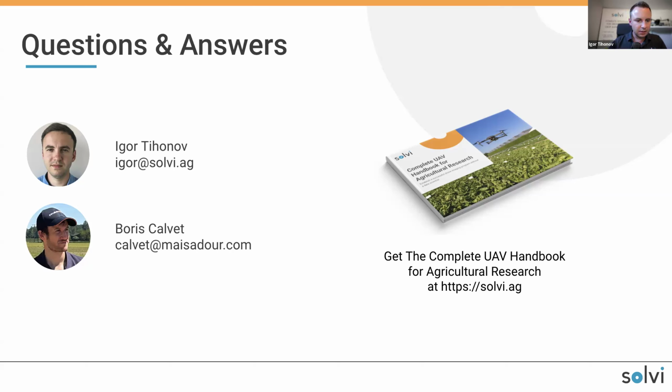All right, let's see if there are any other questions. When using the Mavic 3M for multispectral images, if we have a calibration panel, I believe the last webinar suggested taking panel images before and after the flight. Do these calibration images get uploaded along with flight images, or is there a special process? No, that's exactly how it works. So you just upload them along with all other images, and during the processing, these images will be detected automatically and used for calibration.